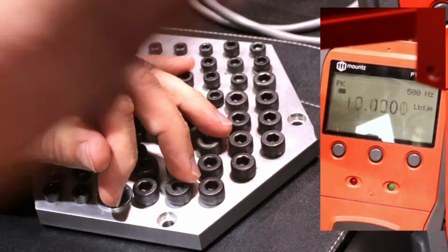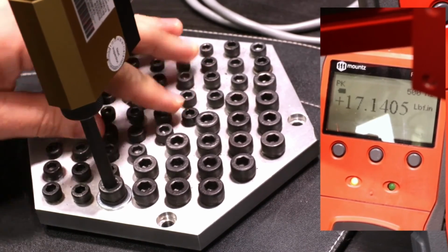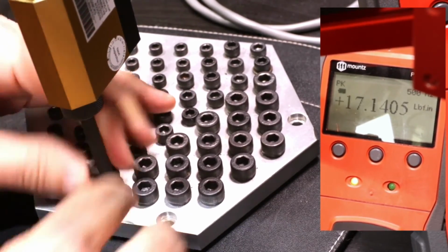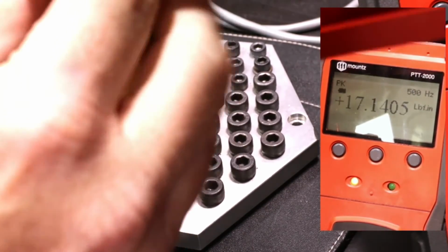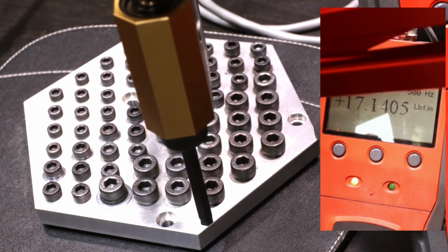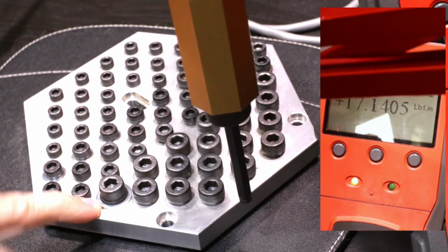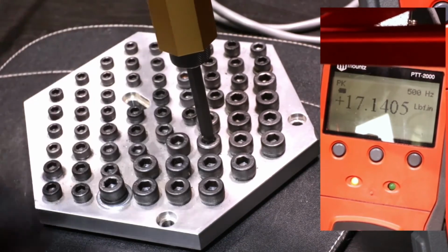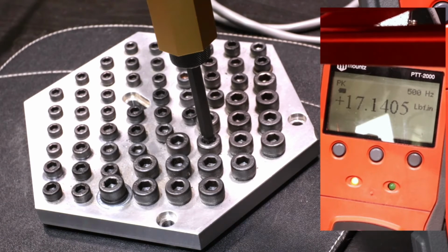And so we have those readings here. And so with this, I have these four fasteners. Three of them are kind of simulating a more hard joint, and then the last one is simulating a softer joint where we have a washer and then a gasket as well. This is so we can do the first movement test. It's very difficult to do the first movement test on a really hard joint because you have a lot of friction to overcome, so it can be very, very difficult. In this case, I will do the first movement test on the softer joint.